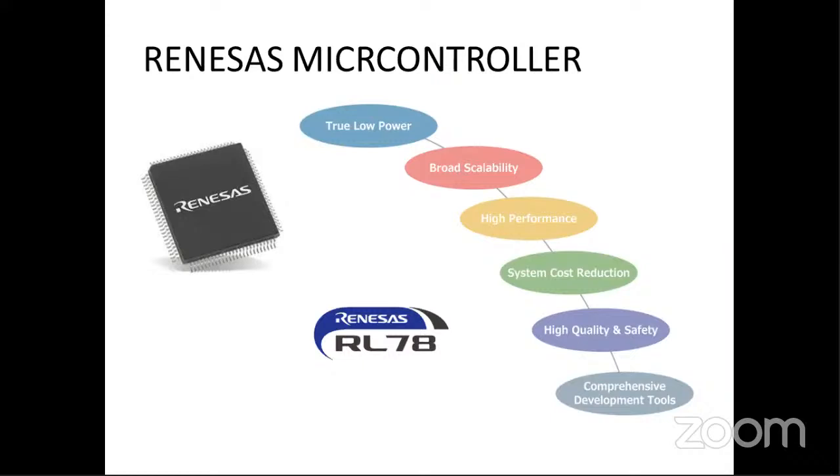Along with that, there is a 20-bit address bus and a 16-bit data bus, due to which the maximum internal memory which can be interfaced with this controller is 2 to the power 20, which comes out to be 1,048,576. That is 1 MB of memory locations which can be interfaced with this controller. And this family was introduced a decade ago, in 2010.